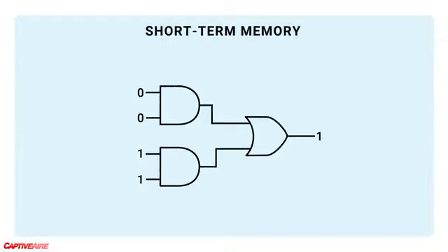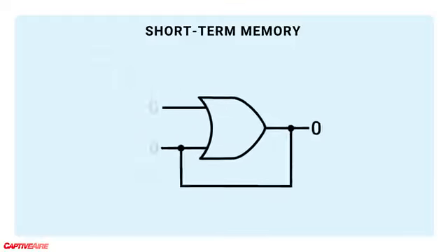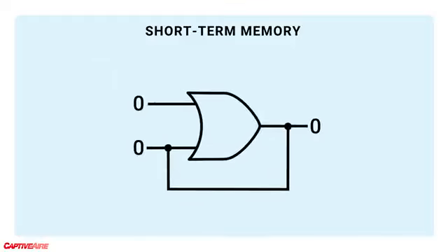So far, we've only been talking about logic gates in a linear fashion. But interesting things happen when you feed the output of a logic gate back into its input. Take this OR gate at the most basic level. If we wrap its output back to one of its inputs and provide a 1 to its other input, its output will stay as a 1 even after I let go of that other input, and it will stay like this until I disconnect all power to it.